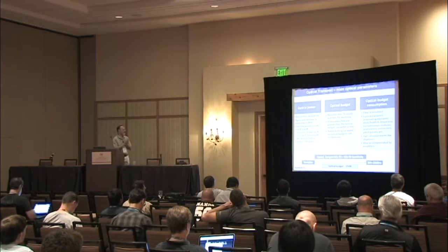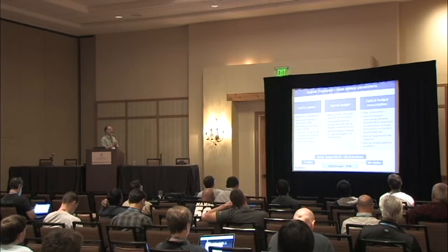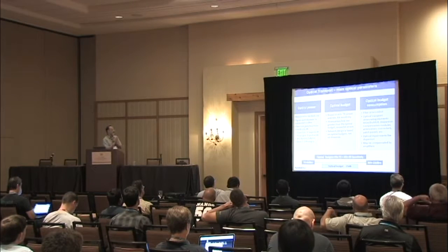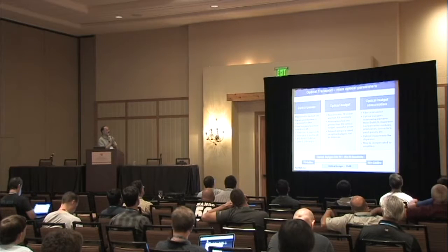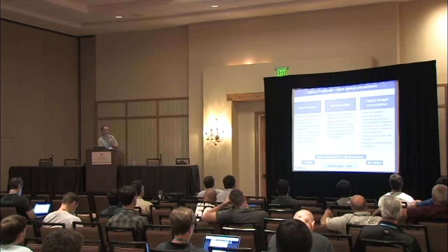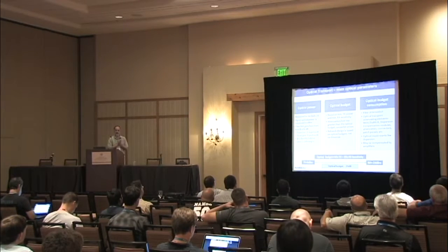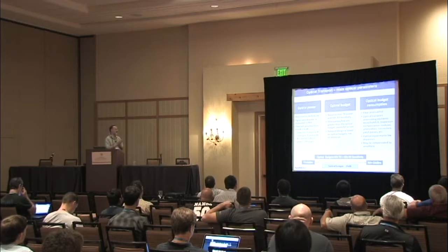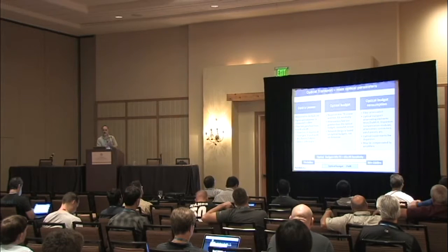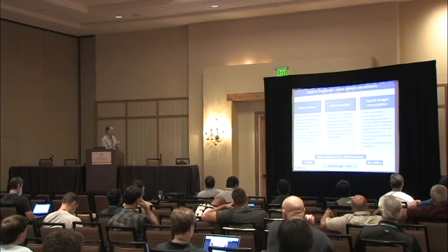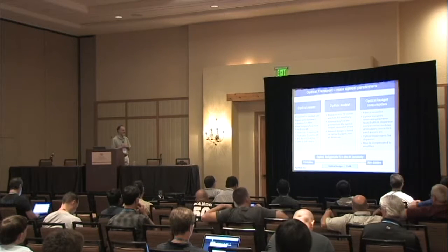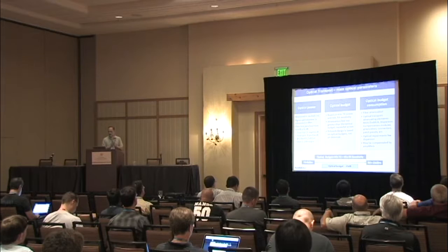So let's look at the basic parameters of an optical transport. First of all, optical power is measured in decibels. Signal optical power is measured in dBm, decibel-milliwatt. And the fiber link loss from A to B is in dB. If you have a power loss, you incur an attenuation, it's negative dB. If you have a power gain, let's say an amplifier or transceiver, it's a positive dB. Typical in C-band, you consume about 1/4 of a dB per kilometer. Those are the basics. And in general, when you do an optical design, leave a little bit of margin beyond what your calculations are.